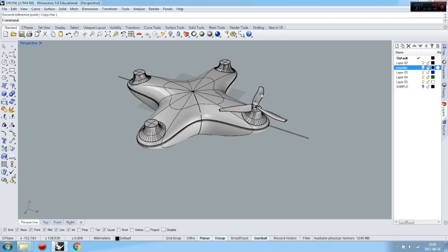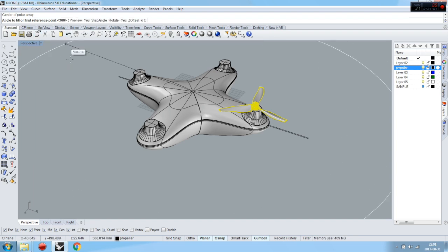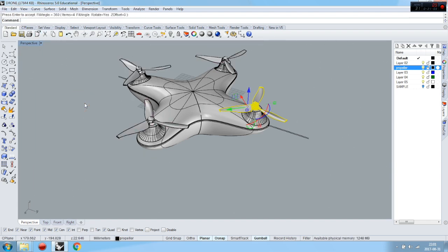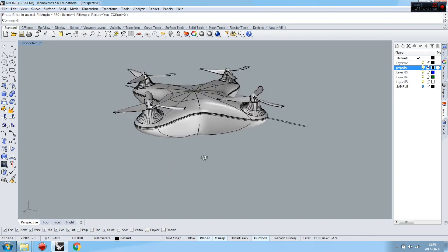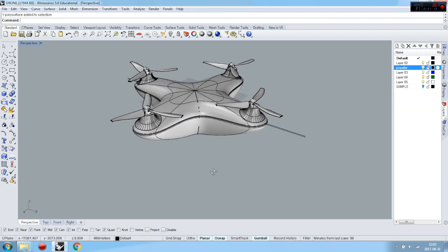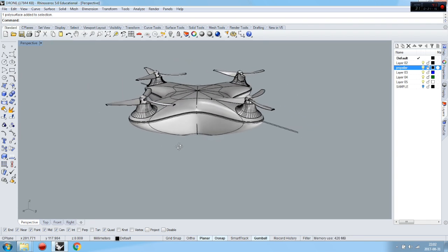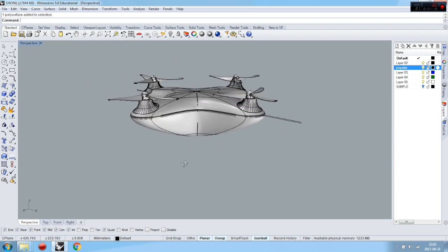And now actually we need to copy this by using a polar array and using the center as the polar method, and then number of items 4, 360 degrees, just pressing enter if you've done it before, and it's okay. I've got a propeller. So now I need to make legs for this. I'm not going to make a camera or any special equipment. You can do it by yourselves in some way. I will show you how I've made my leg.